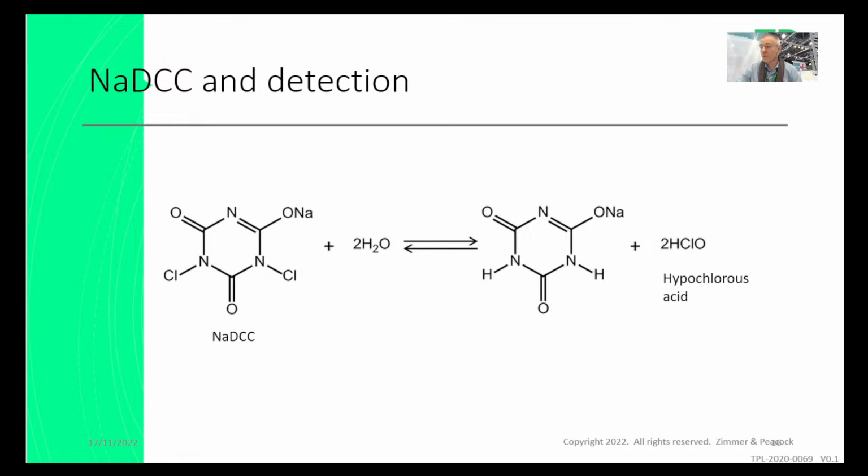NaDCC reacts with water and releases, for example, 2 molecules of hypochlorous acid, and this hypochlorous acid is a form of what they sometimes refer to as free chlorine, but it's basically a bleach. And this bleach oxidizes organic materials, bacteria and viruses, and ends up killing them.